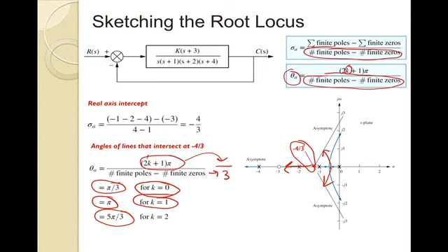As I look at these two poles right here, as I increase gain, the poles at 0 and -1 are going to come together. But instead of going straight up, they have to asymptotically approach those lines that we found here. That's what you'll see is this curvature of the root locus, and eventually they asymptotically approach that, going off to the zeros at infinity.